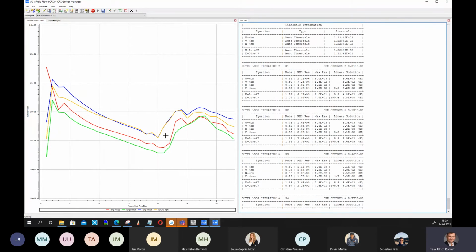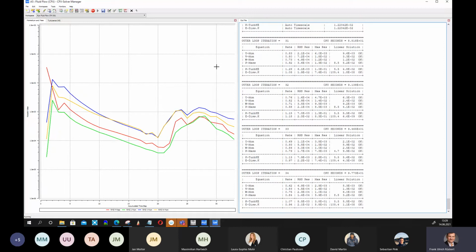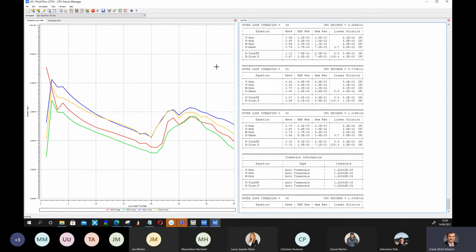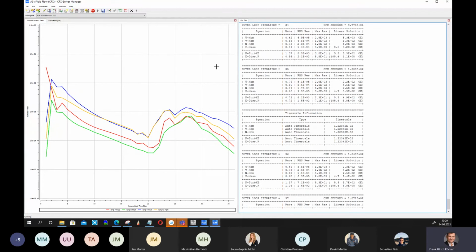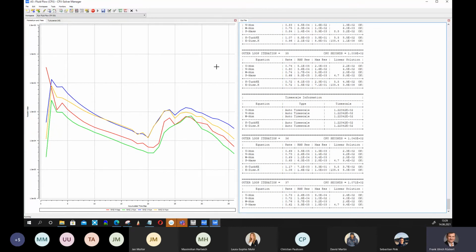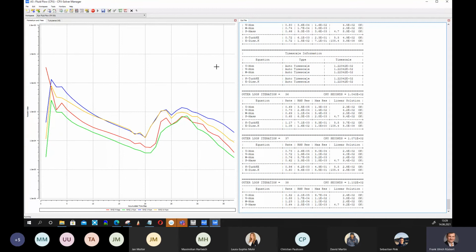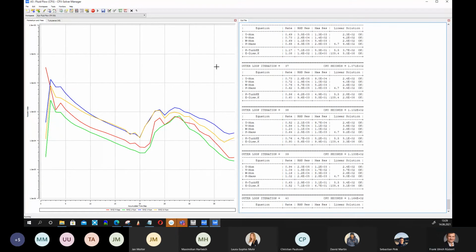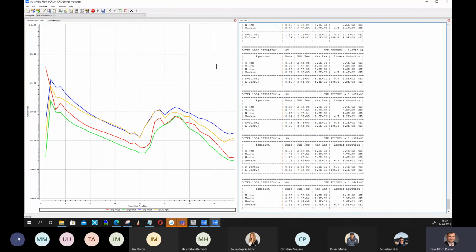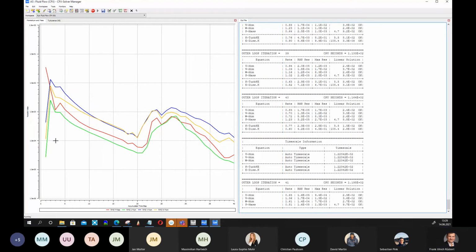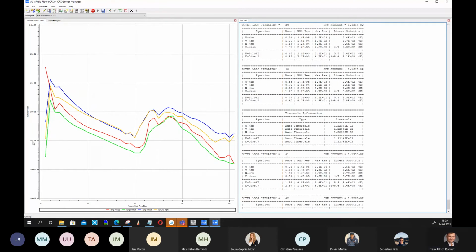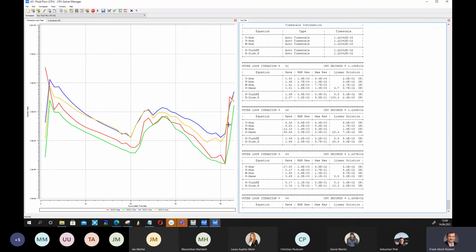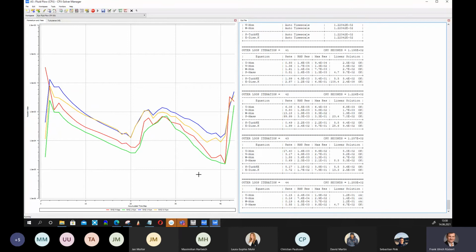So the solver has a bit more work here. Maybe there's some swirl or some turbulent effect around the airplane. This can influence the numerical simulation, but now you see the problems are solved. The residuals go down. They are 10 exponent minus 4. Oh, they go up again.